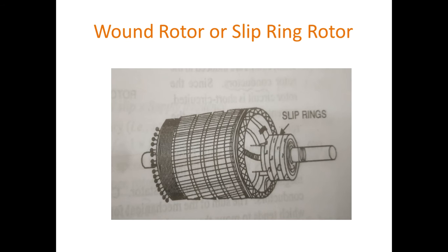The three brushes are connected to a three-phase star connected rheostat. That means we can include external resistance in the rotor circuit by the use of the three-phase rheostat.